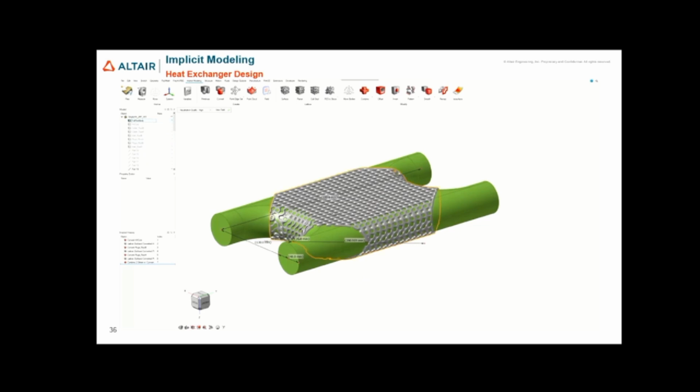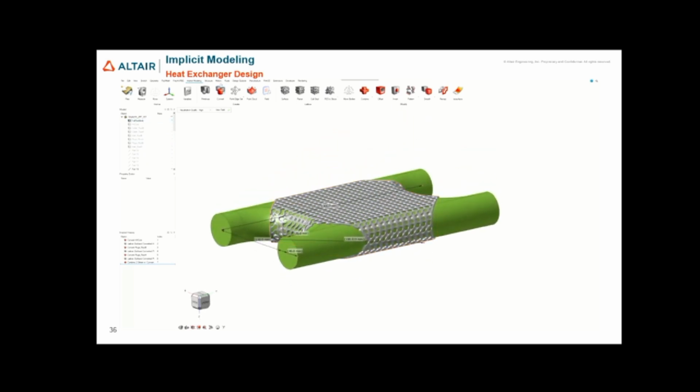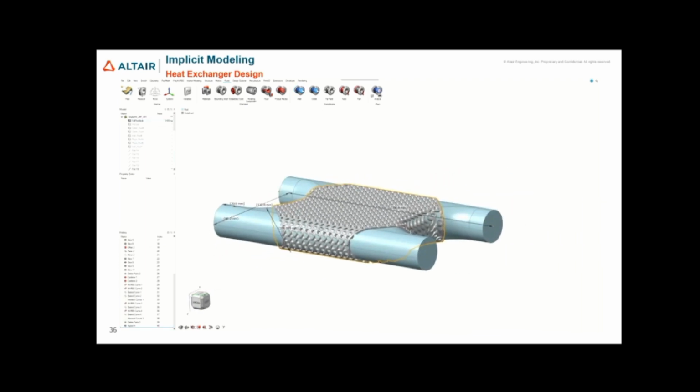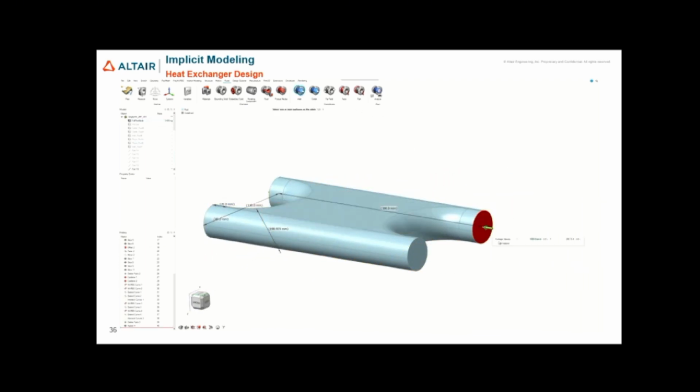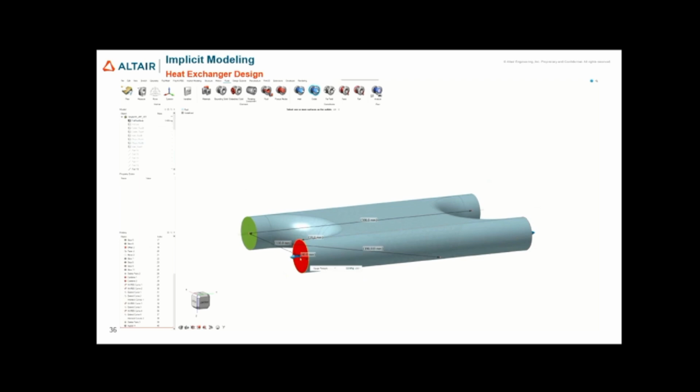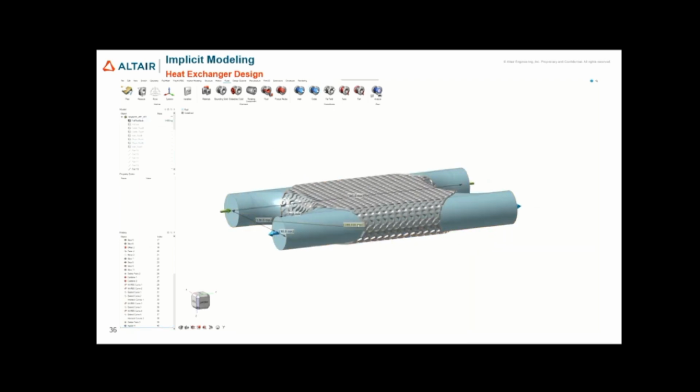And then applying the boundary conditions is incredibly simple. So we just have our fluid domain, which in this case, there will be two fluid domains, but we have the single domain that covers everything. We can then apply materials to individual inputs. So the inlet has a material in it, so you might have two different materials. So it could be air and water or anything like that. And then basically you can put the outlets in, so specify where the fluids are going to escape.